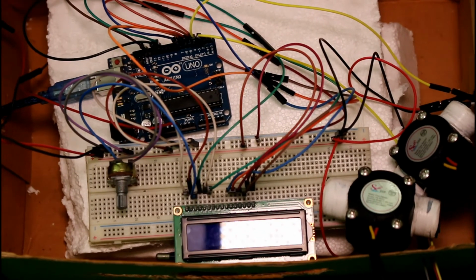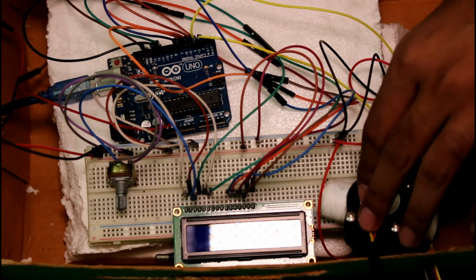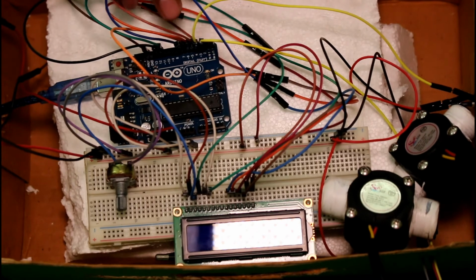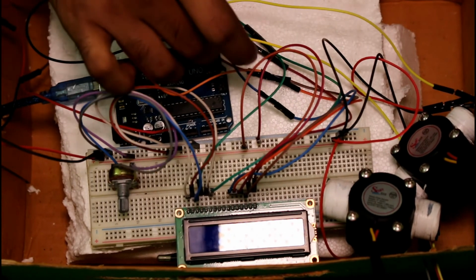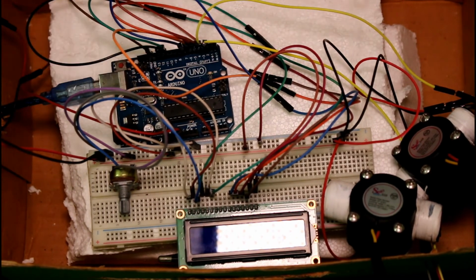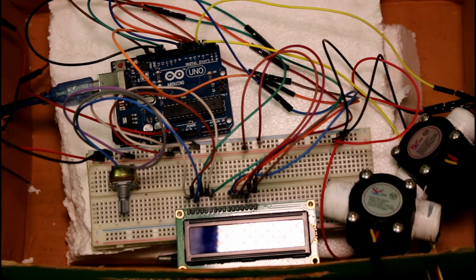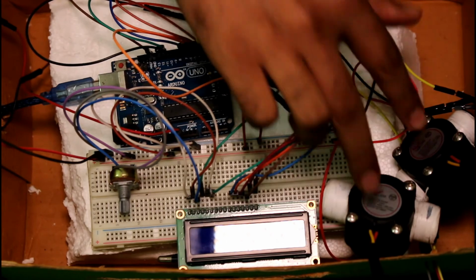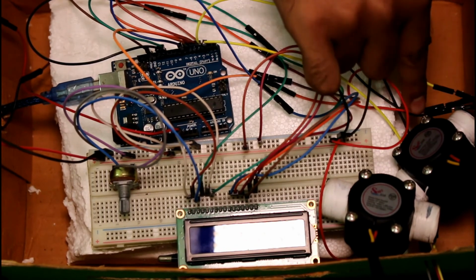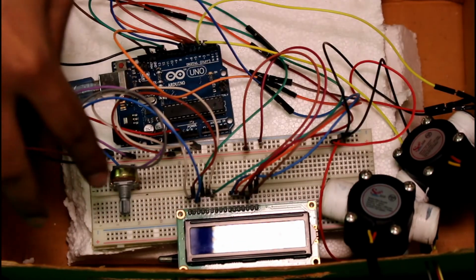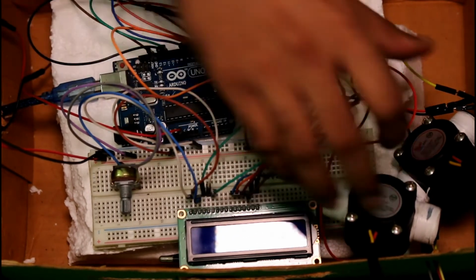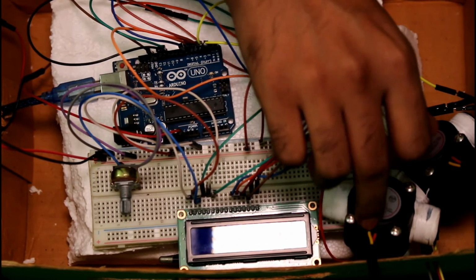First, we have connected the 2 flow sensors to digital pins 2 and 3 of the microcontroller, because only pins 2 and 3 on the Arduino UNO support the attachInterrupt function that we have used to collect the data from the flow sensors. We also connected the ground and power ports of these 2 sensors to the 5-volt power port of the Arduino UNO. This is our connection of the flow sensors.